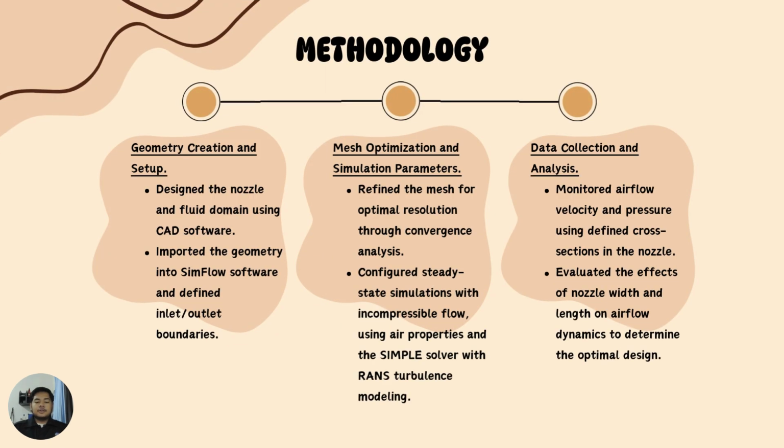To achieve these objectives, the project followed a systematic methodology divided into three main stages. Stage 1, geometry creation and setup. The nozzles and their fluid domains were designed using CAD software. These designs were then imported into SimFlow software, where boundary conditions were defined, including the inlet and outlet parameters for the airflow. Stage 2, mesh optimization and simulation parameters.